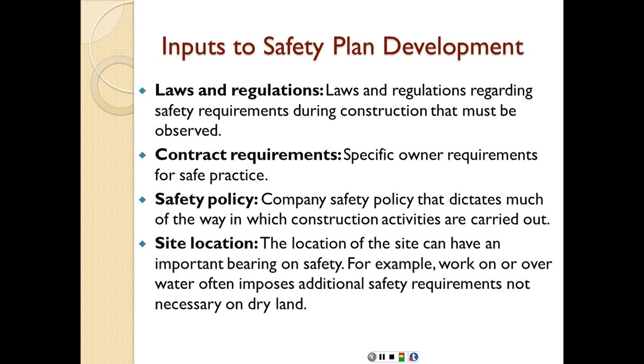The site location. The location of the site can have an important bearing on safety. For example, work on or over water often imposes additional safety requirements, not necessarily on dry land. Especially if you're going to excavate below the groundwater table, now you're working in a wet environment. If you're going to have electrical equipment operating in that location, then we have the added hazard of electrocution. If you're going to work in a deep trench, then we have the hazard of caving in. So again, we're going to look at all the job conditions to try to analyze what are the hazards associated with this type of work.